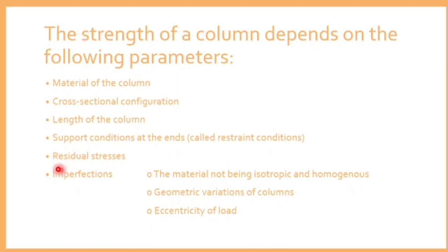And residual stresses. If you want to do research on this topic, some people do projects on design of commercial buildings, design of 12-story structures, some take wastewater, and some do pavement design. You can do your project only on compression members. What you have to do is find the residual stress. Your column will not be exactly rectangular. Slight twisting is also acceptable. So how much can we accept? These things come under imperfection.